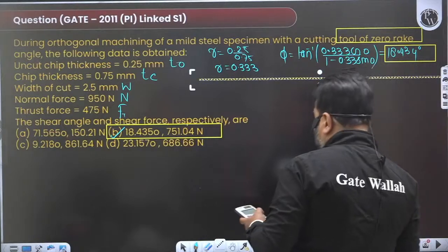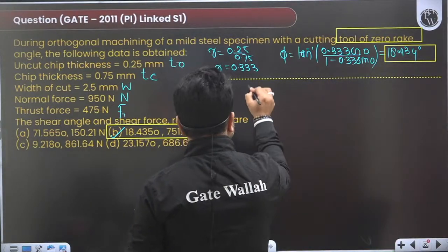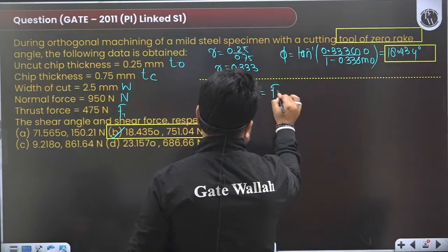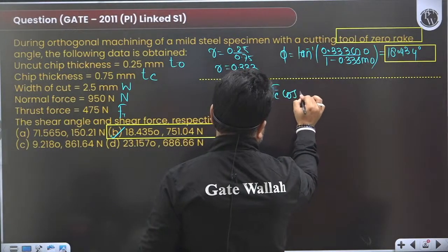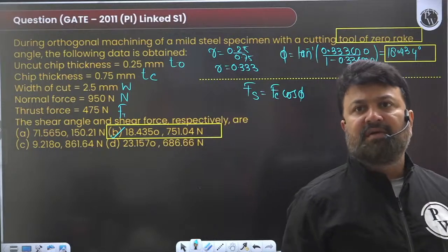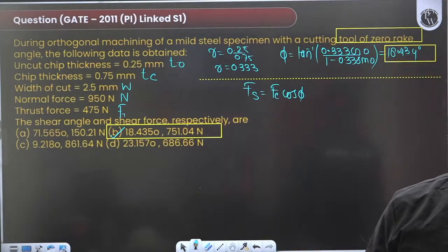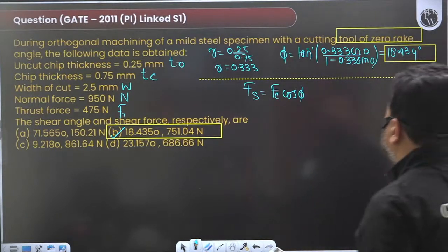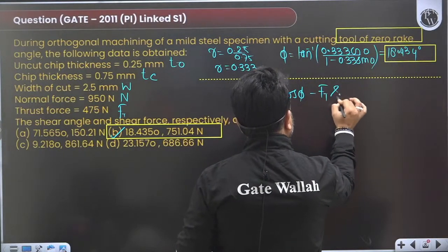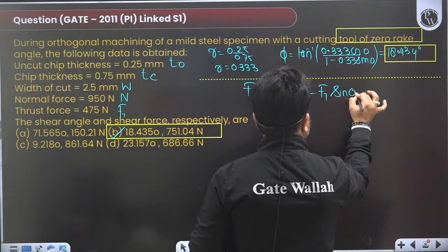Then how can we calculate? We need shear force. Shear force Fs is what? Fc cos phi minus Ft sin phi.